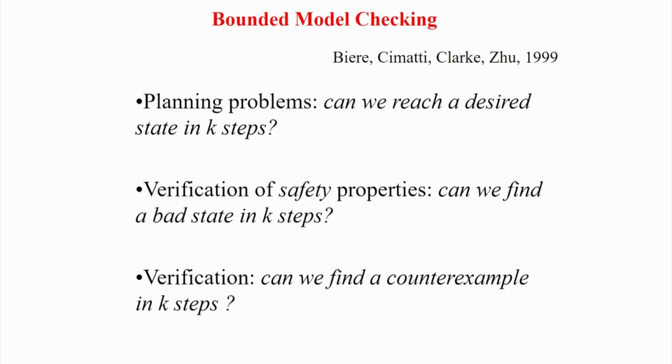Today we are going to see another way of optimization, called bounded model checking. So, what is the core idea? In symbolic model checking, we were at the gate level or bit level. In bounded model checking also we are at the lower bit level only, because we do not have very well matured labeling techniques for the high level diagrams. So, in bounded model checking also, we are at the lower level of enumeration.